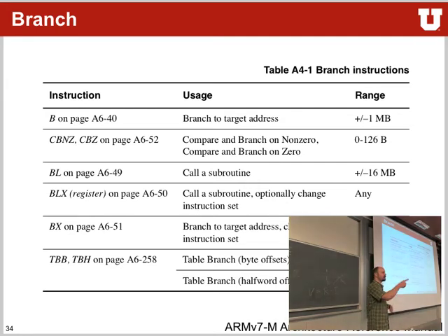Yes? Okay, well, what's the advantage of the different instruction sets? History. It's just how it developed. First came the ARM architecture, then came Thumb, then came Thumb2, and later on they realized, well, we have to have somehow a way of merging them together. And I think later on we will have a slide that will show you the advantages of using a different instruction set. Thumb2 has this mix between 16-bit and 32-bit, which is new, so you can really optimize your code and make the code base smaller. Very important for microcontrollers, not as important for application processors themselves.